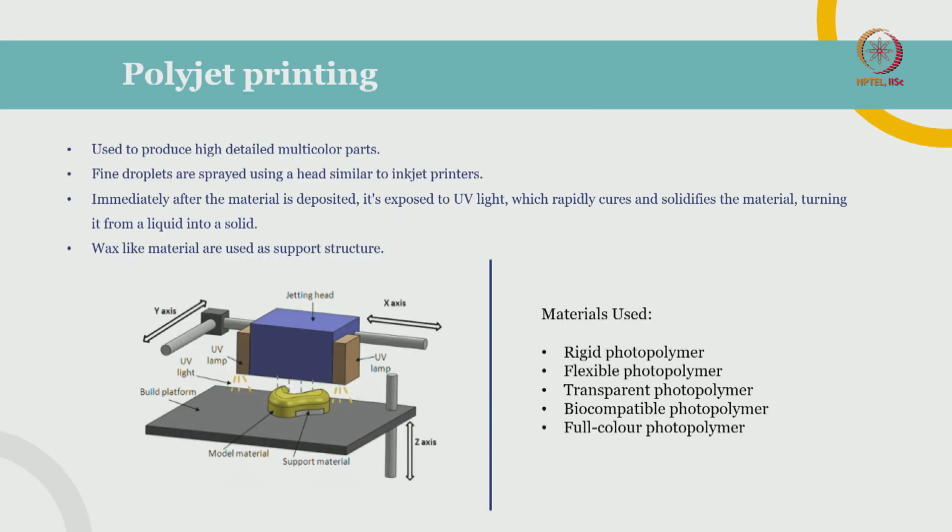So next one is polyjet printing. In binder jet we have a base powder material, and we spray binders, adhesive liquid, over the top of that powder material. So we get a solid mass of object, what we designed in our 3D modeling software. Okay, so in polyjet, how it works is, it has a jetting head, a print head, and that print head sprays liquid photopolymer.